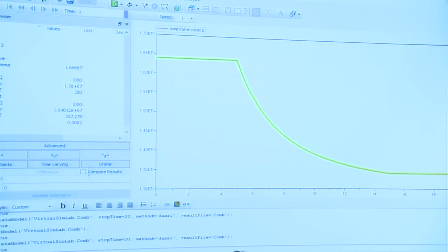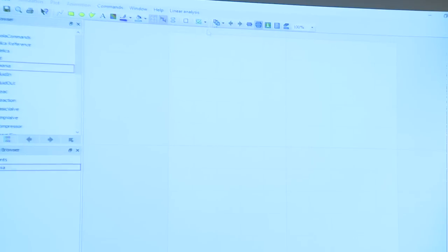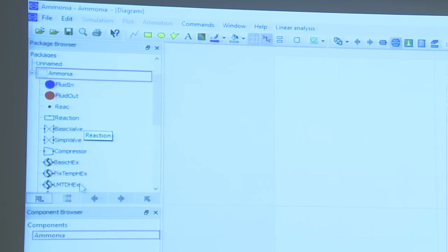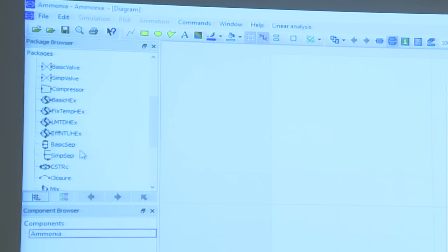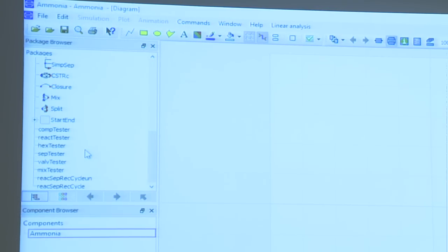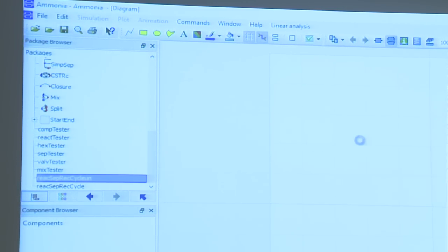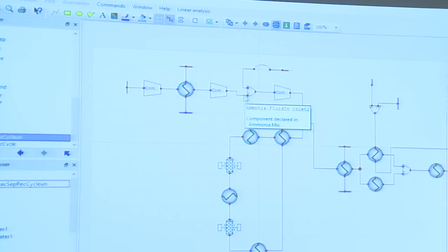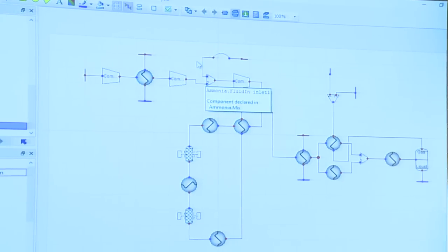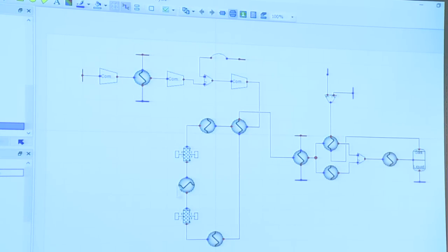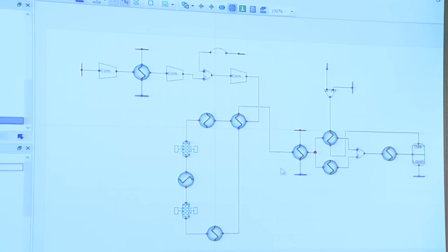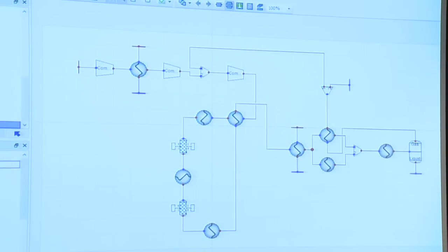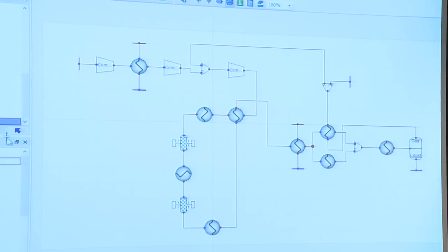And to finish off, I just want to show you what I work with. This one here is just my package which I designed for a simplified ammonia loop, consisting of valves, compressor, heat exchanger, simple separator, and everything together. This one here is set in an unconnected manner. So we have just a normal compression train with interstage cooling, recycle coming in, heat integration around the reaction section, cooling, recycled purge. Also existing in a connected manner.